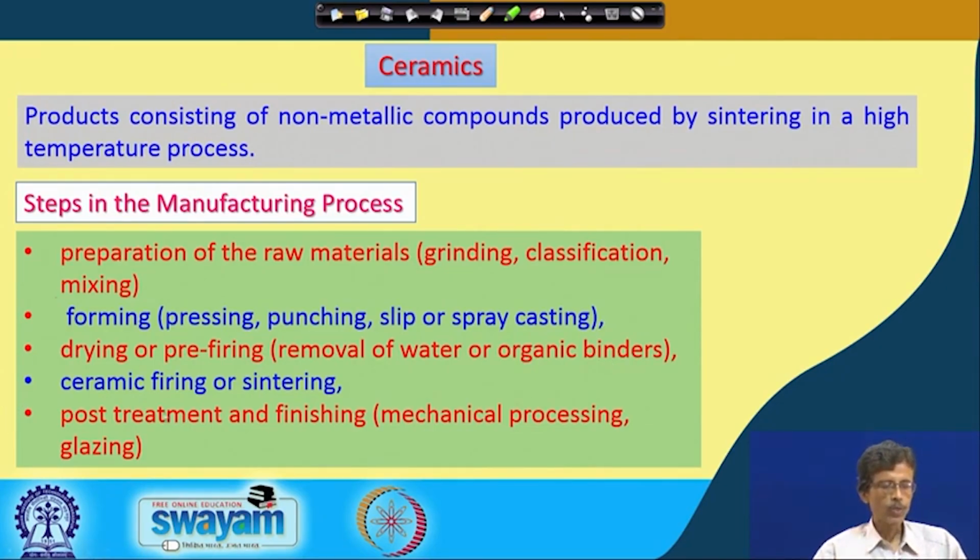In the fourth step, what do we get? The actual firing process. The actual firing process is the ceramic firing process, and then the sintering. Basically, when we heat it, the gas molecules come out through the bulk material, so you get a fluffy material. When all these gas molecules have escaped completely from the mixture, your material settles down and is in the sintered phase, and while sintering it sometimes forms a glassy type of material. So we also get a sintered bed within the crucible if we heat everything in a crucible.